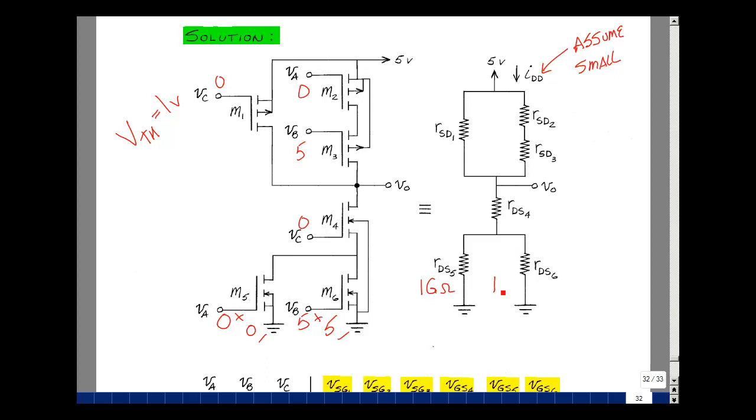It would be something small, say 1 ohm. The voltage across here is going to be 5 volts minus 0. This is 5 volts. It would likewise be an ohmic. Between here and here, I have 5 volts again, 5 minus 0. So that would make this a low resistance. The low resistance here, I've got a small current, and this would be sitting at about 5 volts. The voltage between here and here would be 0. Put this in cutoff, or 1 gigaohm.